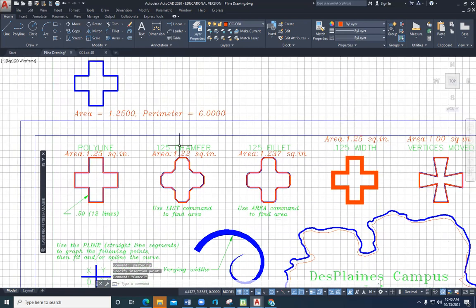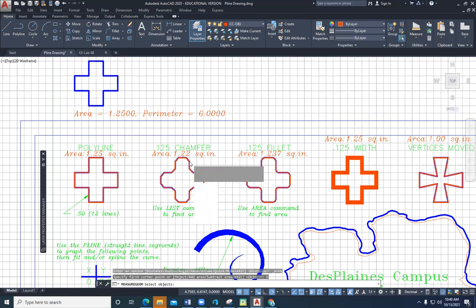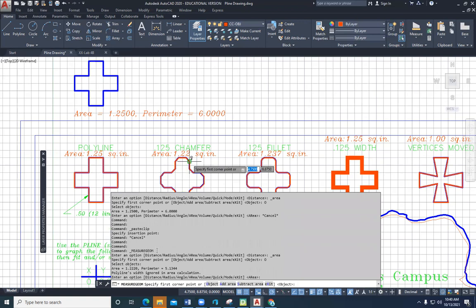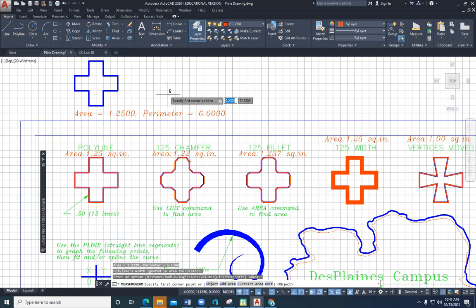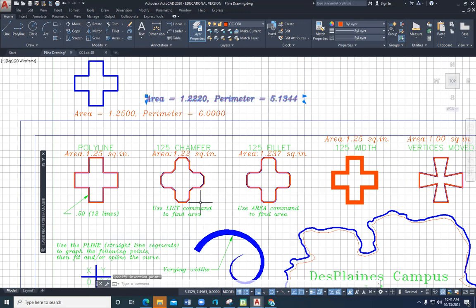And you'll do the same for these other objects as well, where you can calculate out the area with the area command, down arrow, object, select the object, and then it calculates that out. You can hit enter, F2 key, and then I can select that information, Control C, and then I can come up here and paste it, Control V. And I think in the video, I put these above, and so we can just copy this one here.